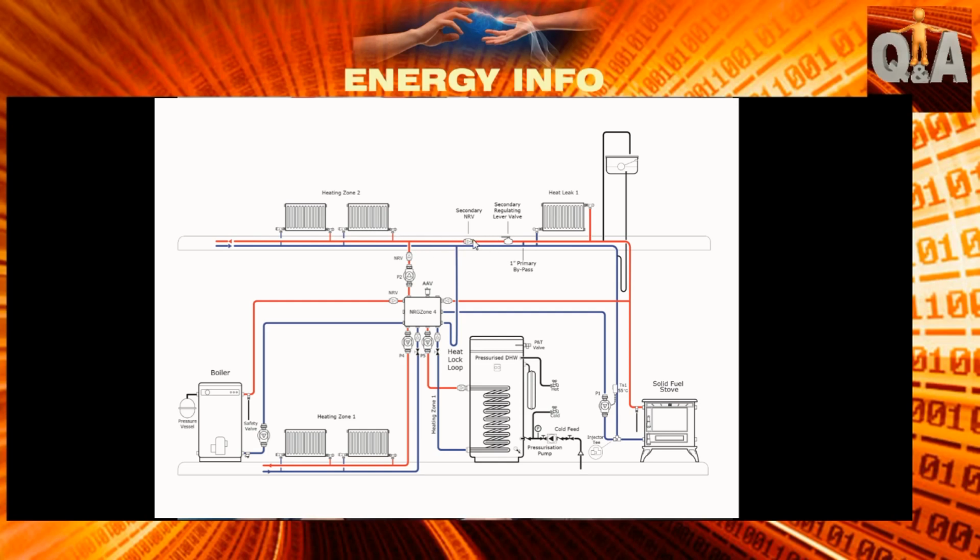When the pump comes on, the water now travels over to your manifold distribution system, for example the energy link, so you can have pressurized water because you're not heating the water directly from the stove. But if the pump is pointing towards your upstairs radiators and it's pushing water up, the water is flowing towards those radiators, but also it's pushing towards the non-return valve, and so it will heat the heat leak radiator as well. There's a little balancing valve that you might see fitted just to the left hand side of the non-return valve, or right hand side.